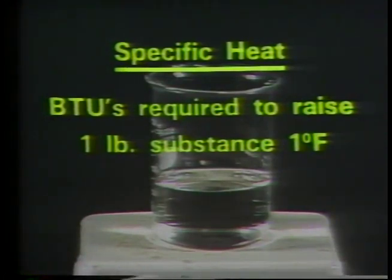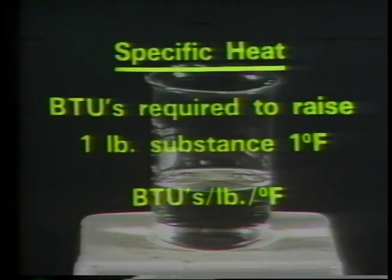Specific heat is the amount of heat measured in BTUs that is required to raise 1 pound of a substance 1 degree Fahrenheit. The units of measurement for specific heat are BTUs per pound per degree Fahrenheit, and the symbol for specific heat is a small c. For all intents and purposes, we say that the specific heat of water is 1 BTU per pound per degree Fahrenheit.